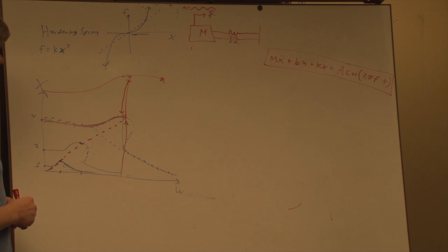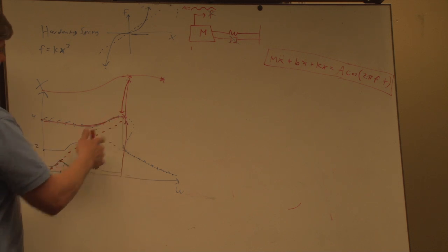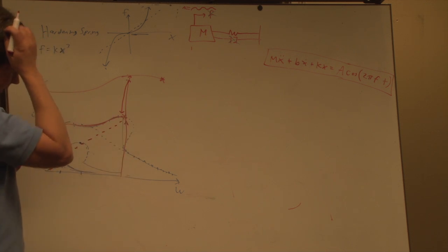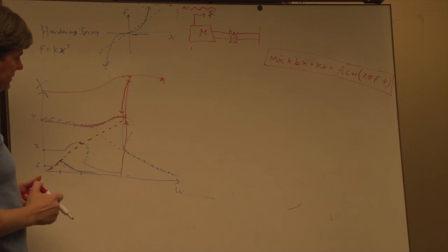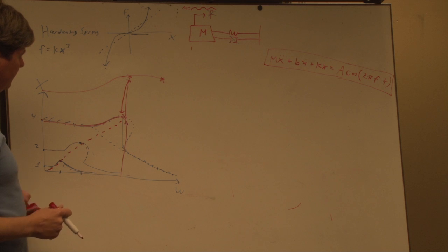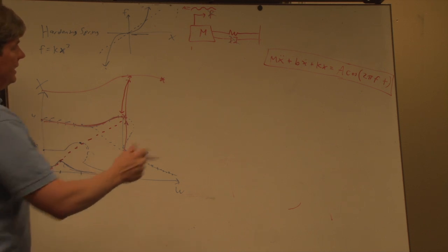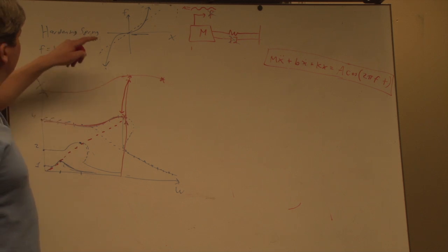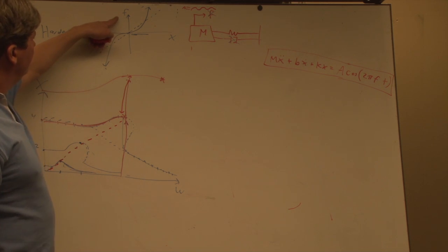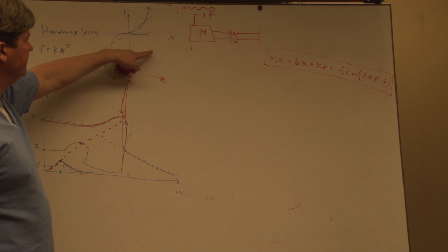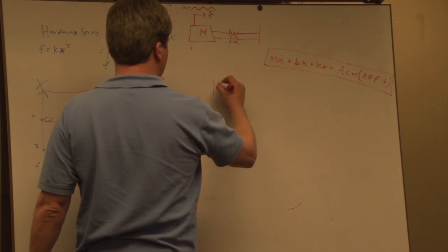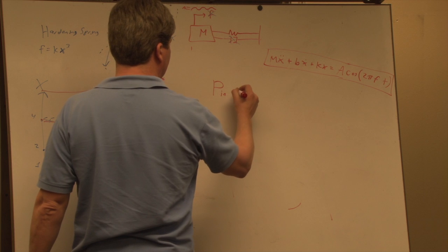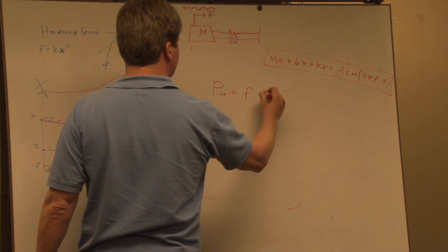Yeah. And what you find when you do simulations of these things is that at your resonant points, you're typically only doing positive work on the system and not doing negative work. And with these sinusoidal systems, you find that your driving force is aligned with your velocity, right? Because your input power, P_in, for a mass spring damper is going to be the force times the velocity.